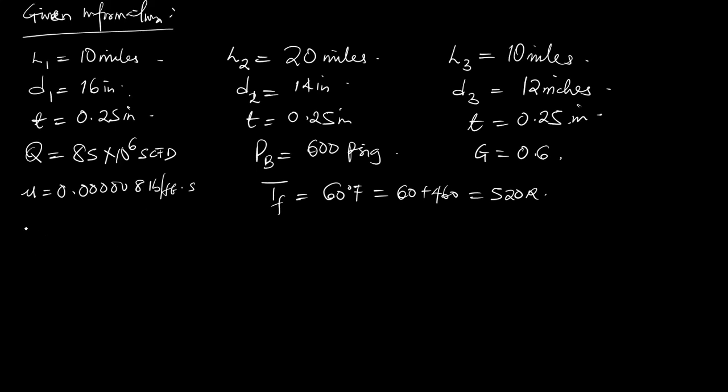Now, the compressibility factor is 0.85. The Colebrook friction factor is 0.015, while the base pressure is 14.7 psia.